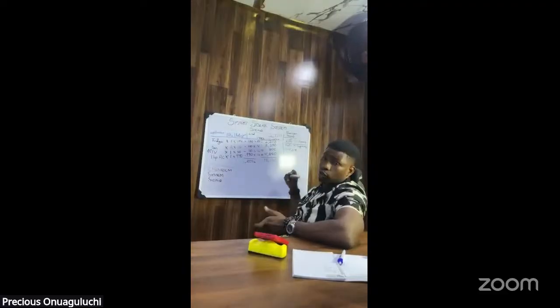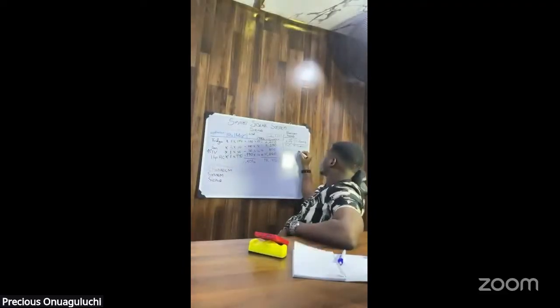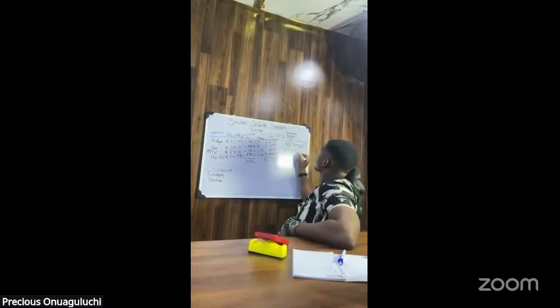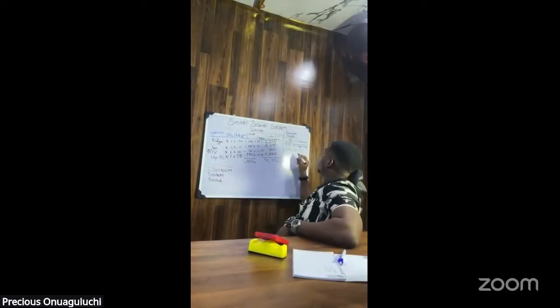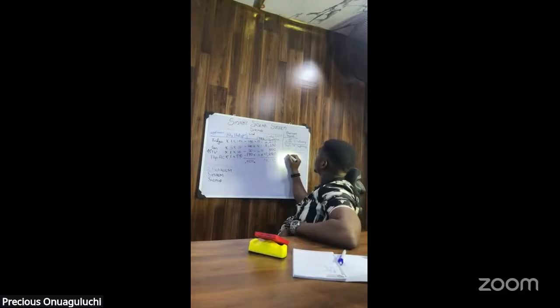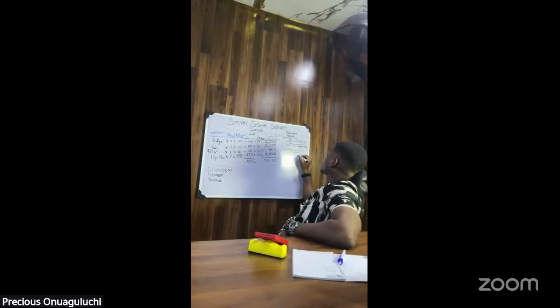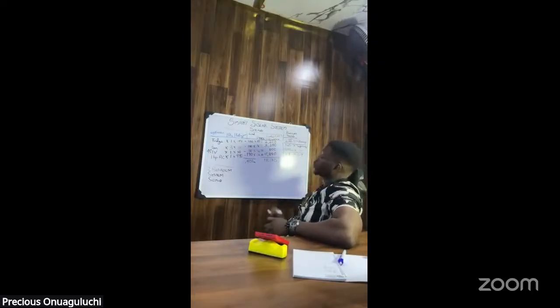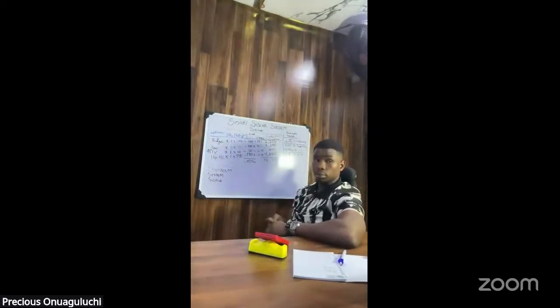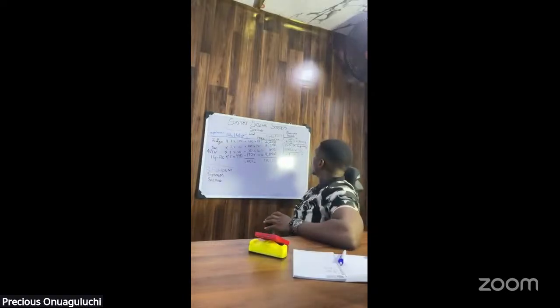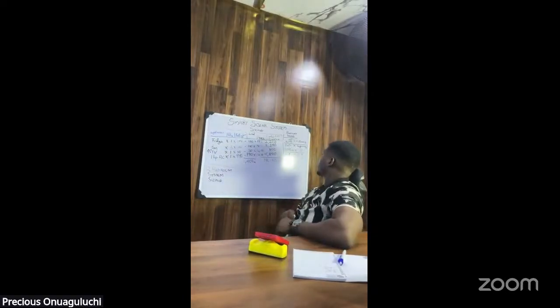Then our days of autonomy, we're going to be calculating 1.5, right? Then because we're going to be using a lithium-ion battery, we can assume that our depth of discharge will be 90%, that's 0.9. And then we can assume that we have a 90% efficient system, right?